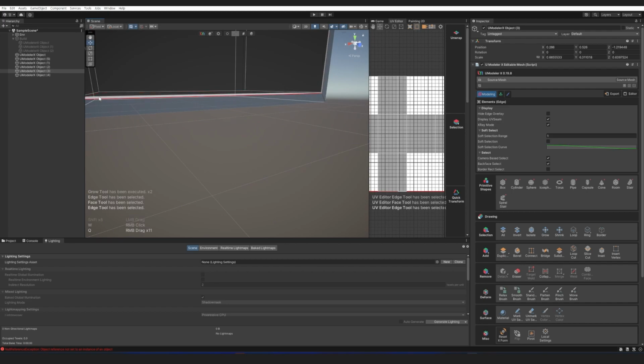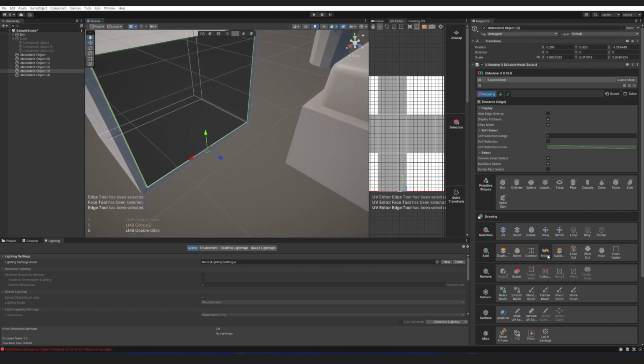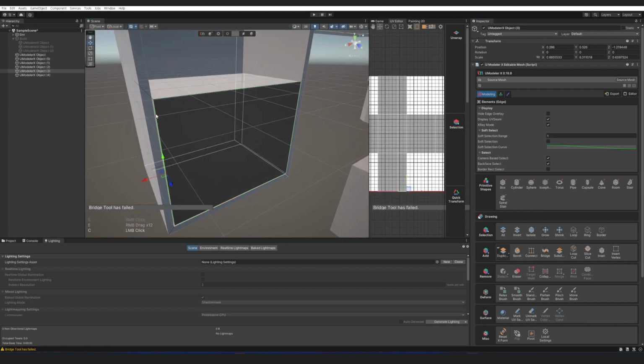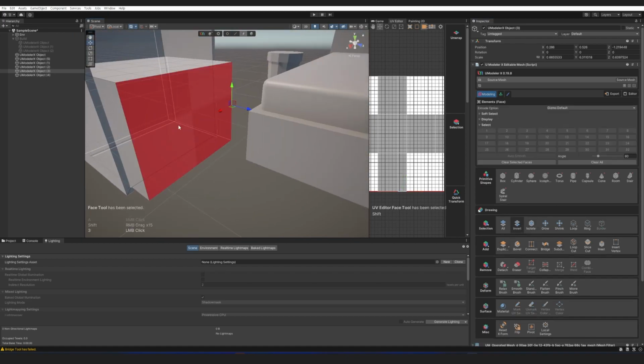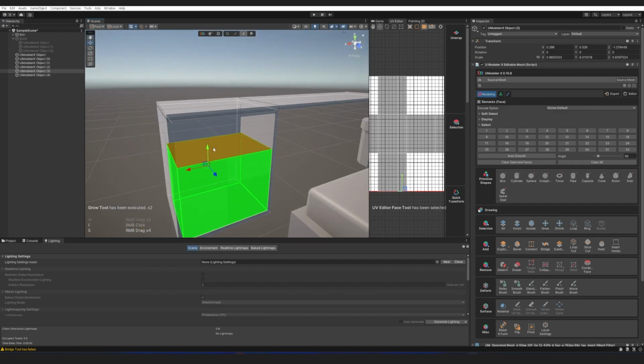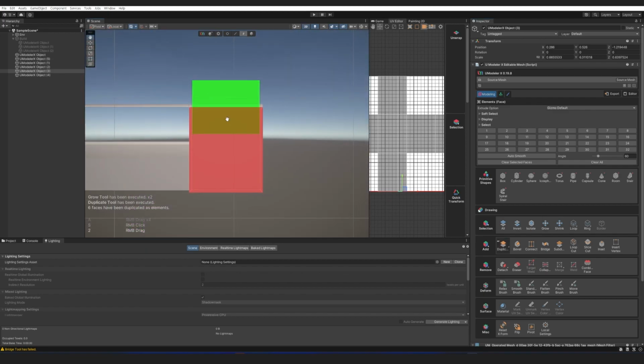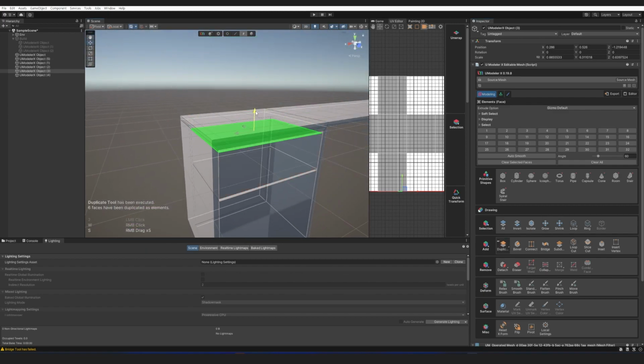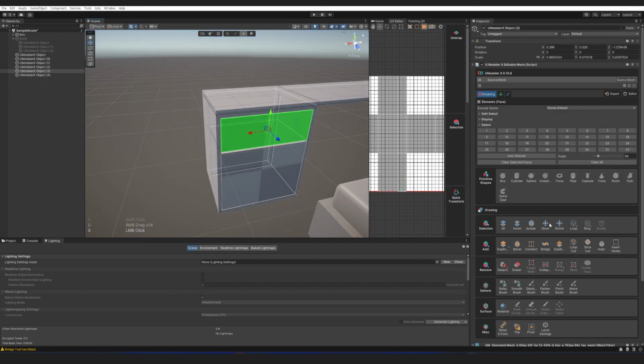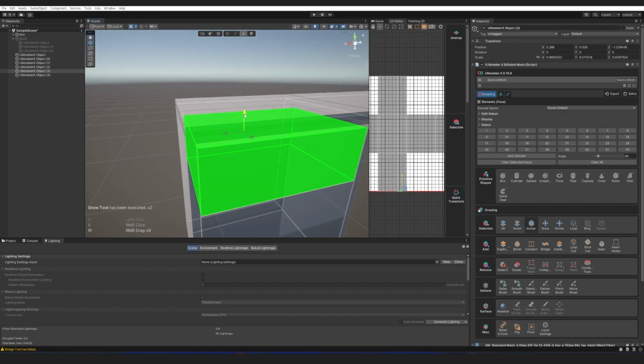The front face of the drawer is not created. In this case, select the top and bottom lines and use the Bridge function to create the face. Duplicate the created drawer to add another drawer above. Duplicate the object, resize it, and place it above the drawer.